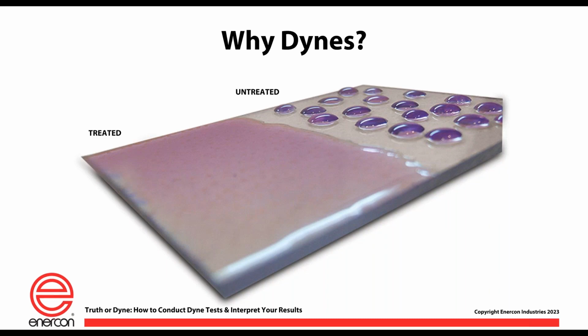So, why Dynes? Well, this measurement method has been a part of our industry for as long as I've been in, and I'm sure it goes way back before me. It's a measurement of surface energy, and it should comport with the Dyne level of your liquid. Now, in the old days, we would have these rules of thumb, which are worth what they're worth. They may not be the most accurate, but they're really intended just to give you a reference point in your head, some place for you to understand. And in the day, they would say things like, well, you should have a Dyne level that's 10 dynes or greater to get a liquid or a coating or an adhesive to wet.